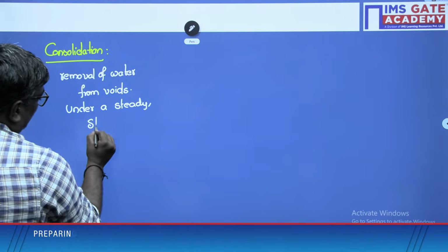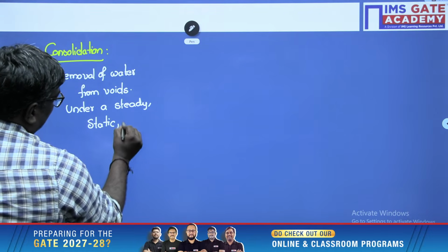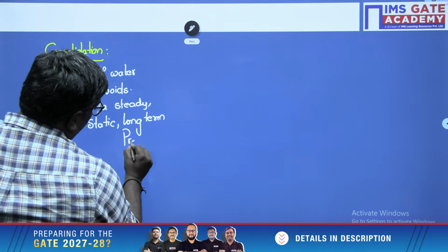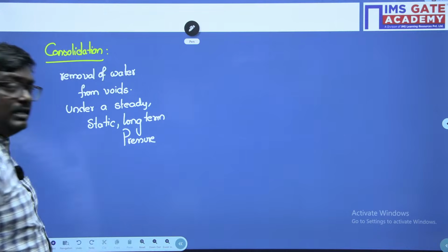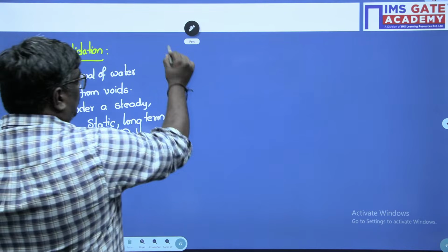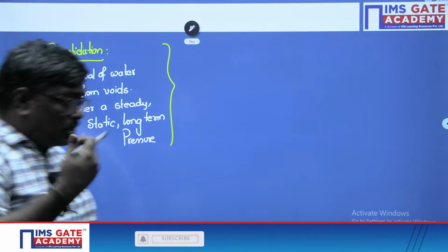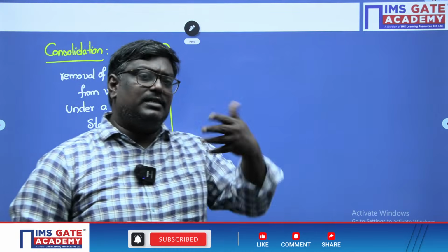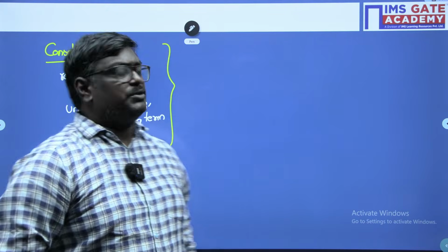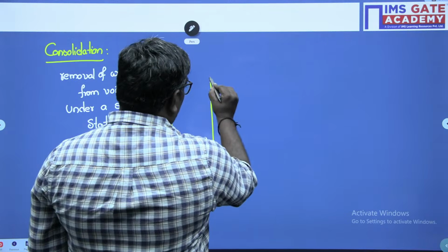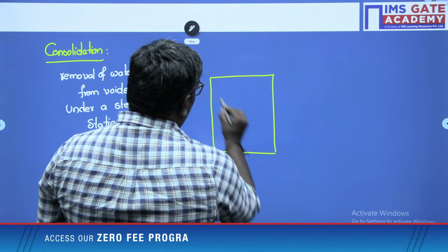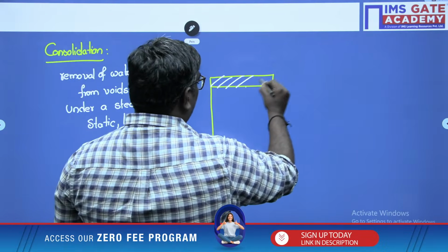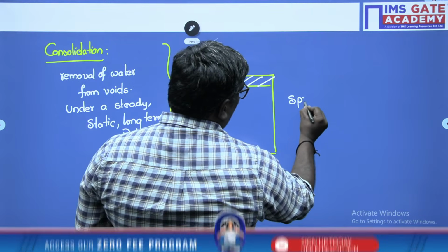Sir, if you see the Leaning Tower of Pisa, the major culprit for the Leaning Tower of Pisa is nothing but consolidation. Okay, sir. Now see students, consolidation happens beneath the structure, that is, it happens in the substructure. So here Terzaghi has given one standard model to understand this, which we call the spring analogy model.